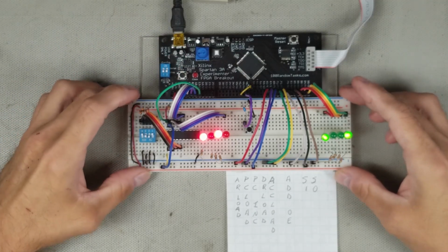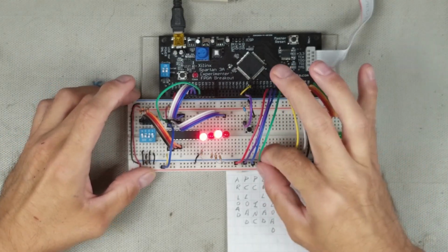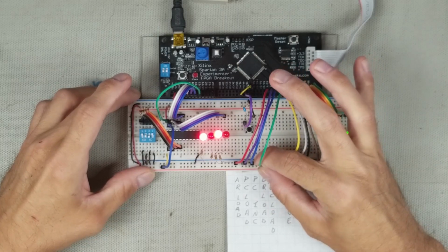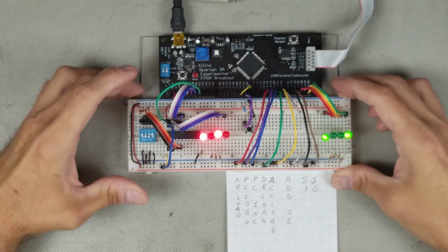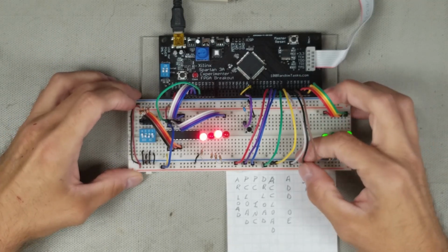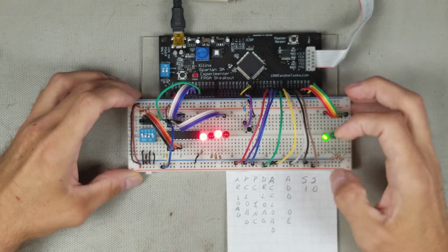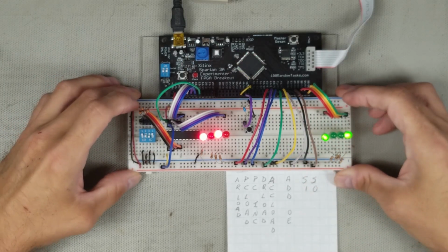Now let's put the program counter into the data register. For that, I'll set the PC increment back to 0, the DR load to high, and cycle the clock. If it loaded correctly, then by setting the select lines to 0, 1, the same value should be shown on the LEDs. Perfect.